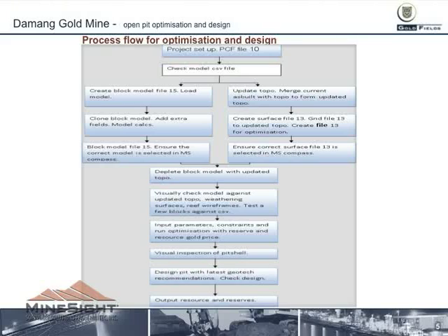After that, we do the input for the optimization. We do visual checks of the pit shell. Then we go on to design with our good old pit expansion tool. After that, we go on to calculate our reserves.